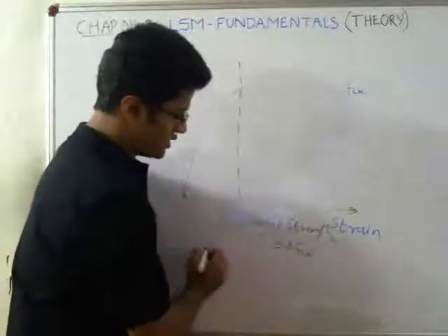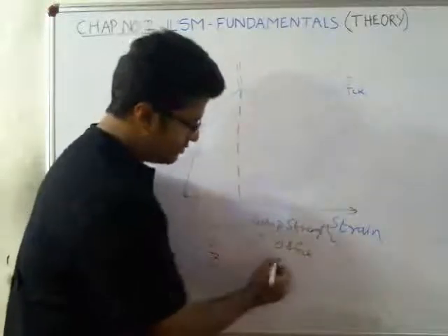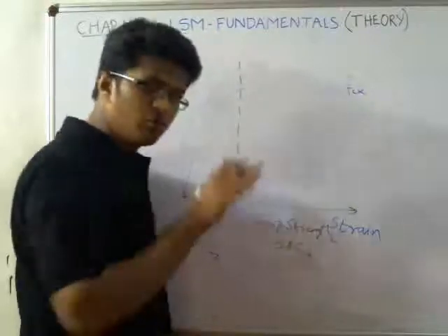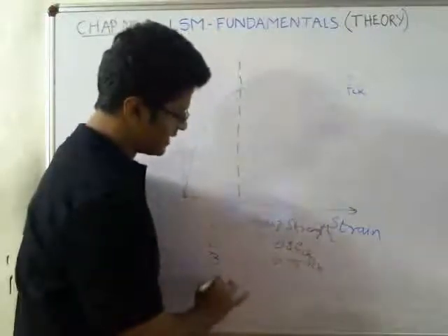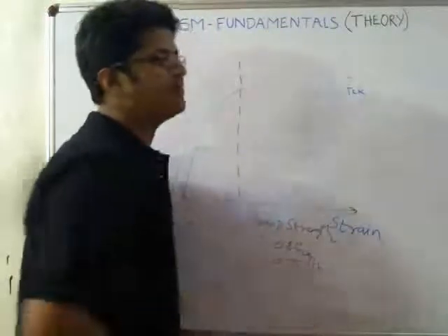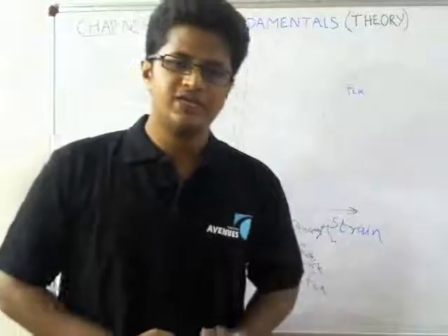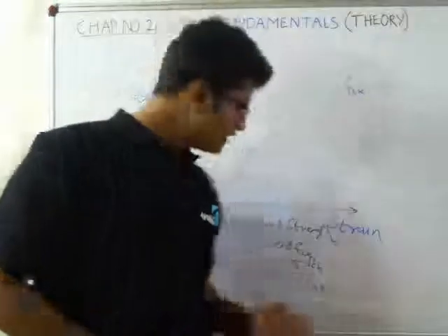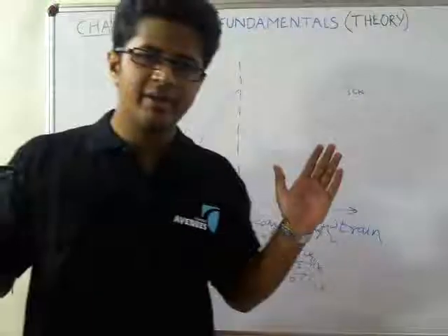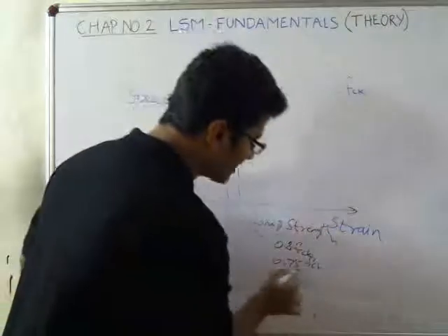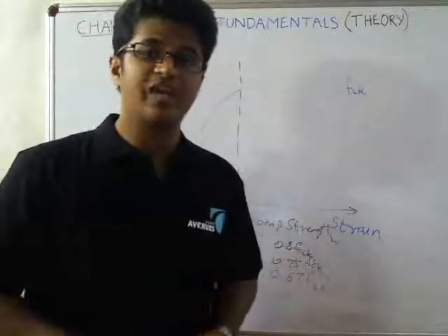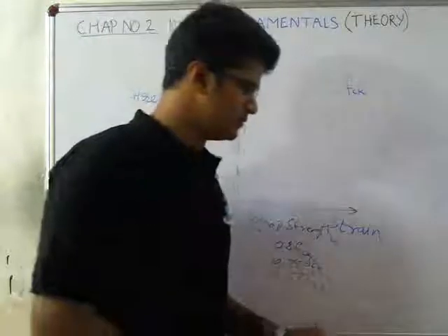As you increase it, it becomes 0.75, more or less tending to go lower, and at 4 it becomes 0.67. And experimentally it is proved that above the slenderness ratio 4, this value remains constant. So for a bigger member, we have to consider 0.67 FCK rather than just considering the FCK which we have obtained from the cube test.